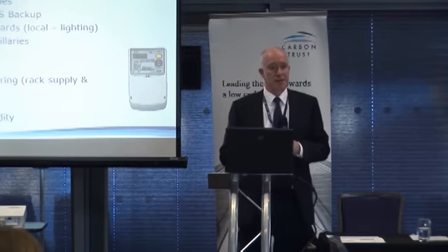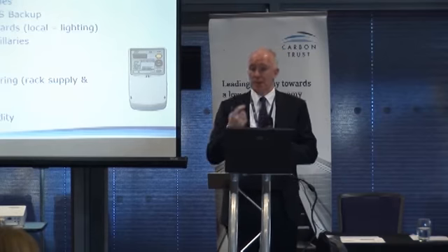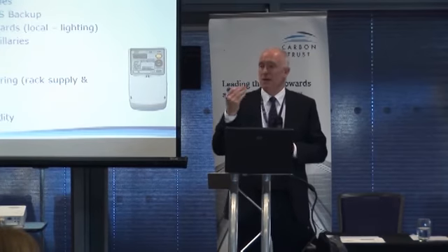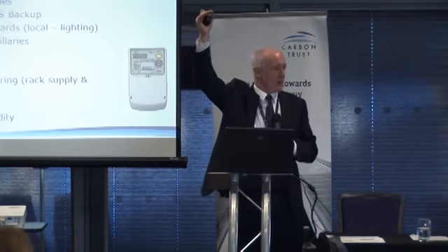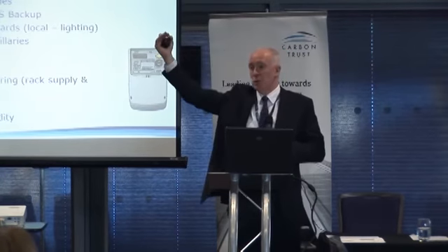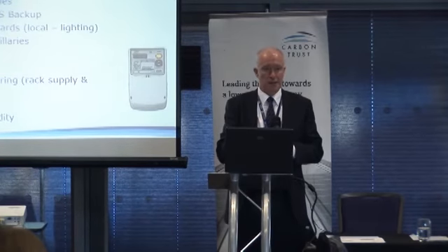The cost of putting in a sub-meter is perhaps £500, so it only takes perhaps a couple of sub-meters. In particular, you'll have to sub-meter the power to the data centre, and you may have to sub-meter the refrigeration plant and the air handling units that may be on the roof or elsewhere. So you've got to bring those two elements in, but it isn't that difficult to bring in these sub-meters.